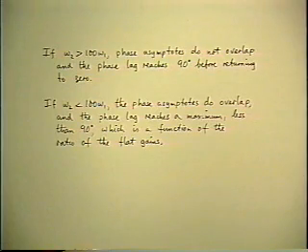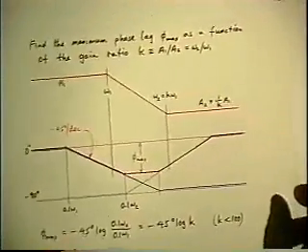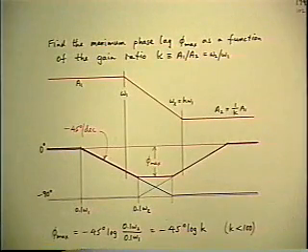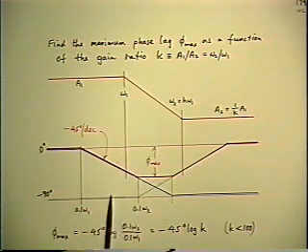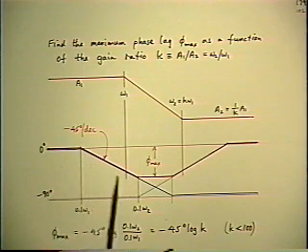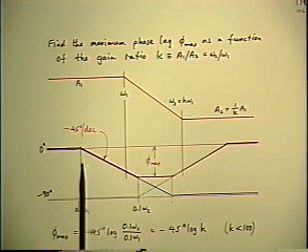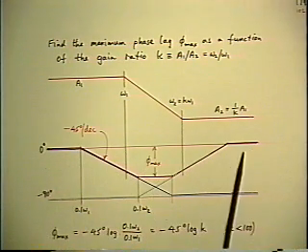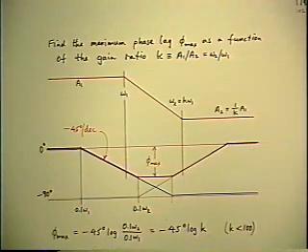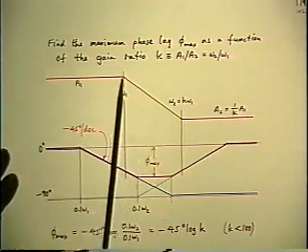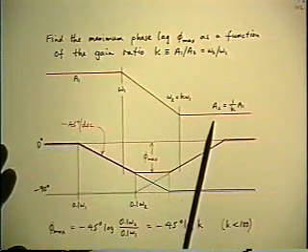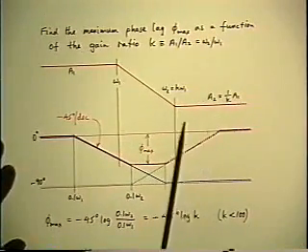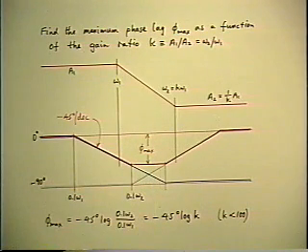And that means drawing a new picture. And in the case of an overlap, you'd have something that looks like this. And this is a very common circuit. It's called a lag lead circuit for obvious reasons. You get a phase lag followed by a phase lead, and the significant feature is that you get zero net phase change from zero to infinite frequency. You start at zero, you end at zero. The gain, however, has dropped off from one flat value to another. This is the reason why this is a common circuit.